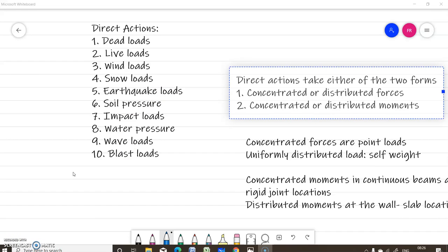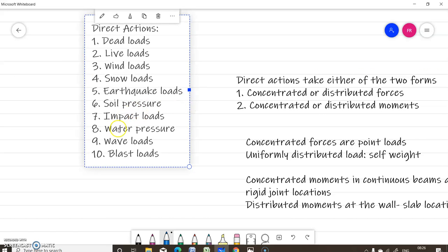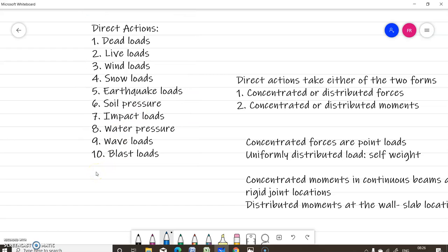The distributions of loads are also idealized for convenience in the form of equivalent loads, like we are taking it as uniformly distributed loads or linearly varying loads, such that they will generally result in safe designs. Loads which are dynamic in nature are often replaced by equivalent static loads for convenience in structural analysis. We are taking it like that. The static loads are multiplied by an impact factor or dynamic magnification factor to account for the maximum amplified response due to dynamic effects due to earthquakes, wind loads, etc.